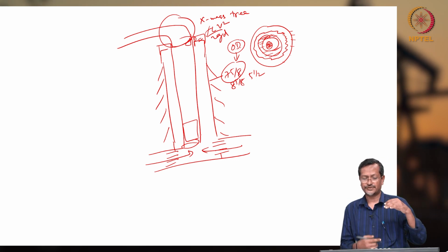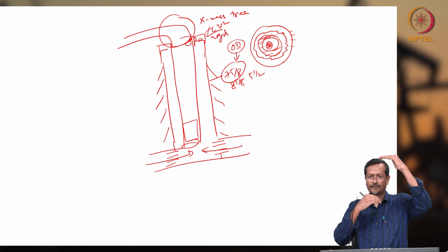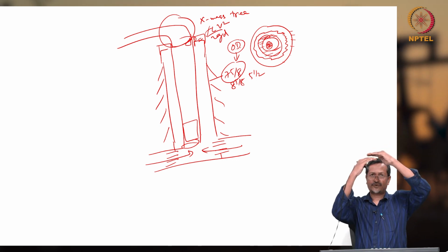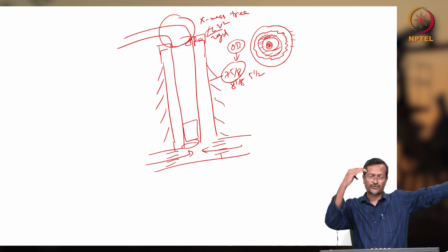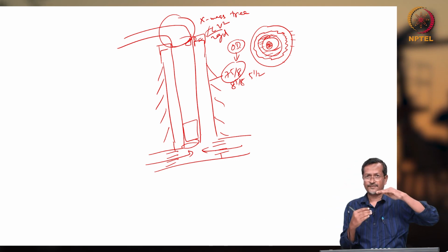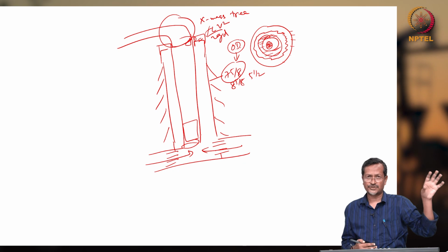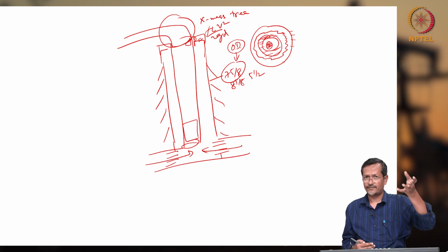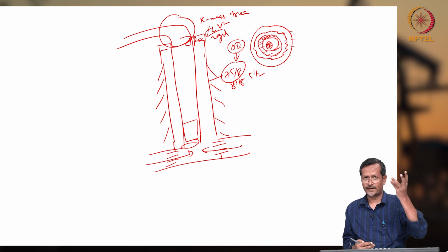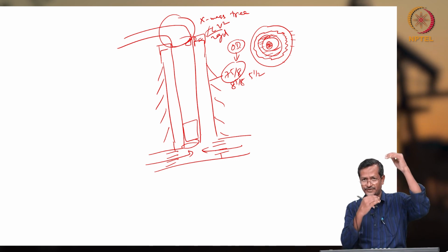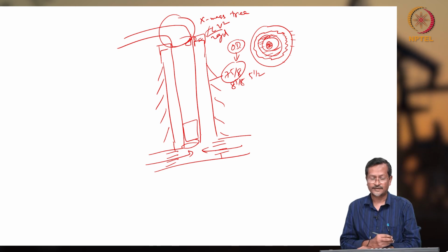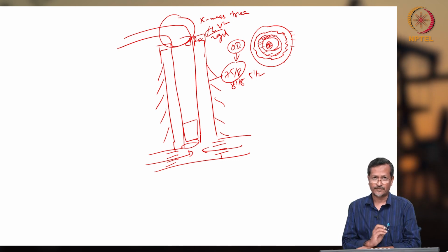It will be developing pressure like total hydrostatic head from pump to the surface. Then at surface there will be requirement of some piping to reach the separator system. If the separator system also requires certain pressure, then you have to calculate separator pressure plus piping pressure plus some elevation, if there is any elevation, or wellhead pressure drop. So those pressures plus frictional pressure drop plus hydrostatic pressure drop, all the pressure you have to calculate, and that much of head the pump must be developing.